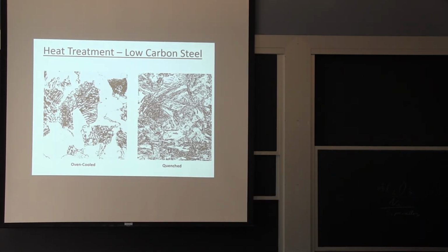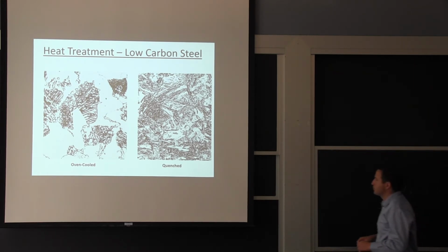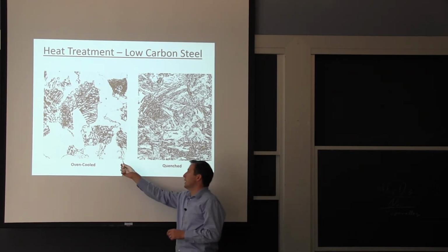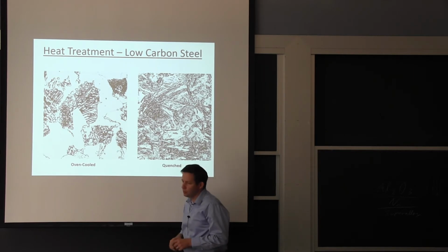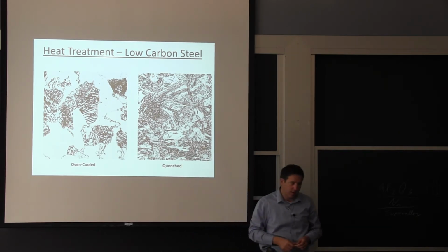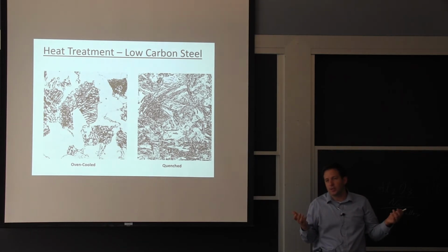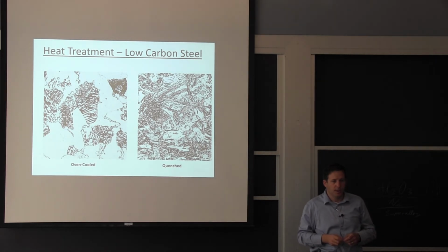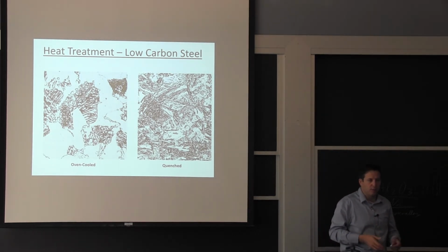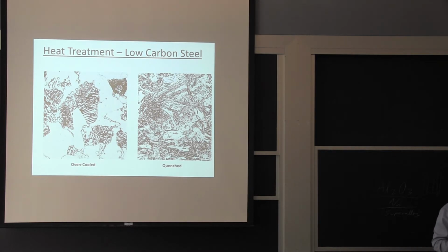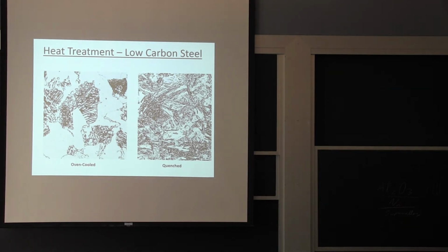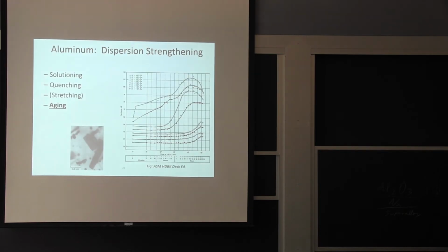And in this process, you change the austenite, that again is non-magnetic, into steel that is ferromagnetic. And if you put enough alloying element, really that's how you get our austenitic stainless steel. You prevent that transformation from taking place, so you keep the high temperature phase all the way to ambient temperature and lower. It's good because steel tends to be brittle at low temperature. We haven't had the time to talk about that too much.